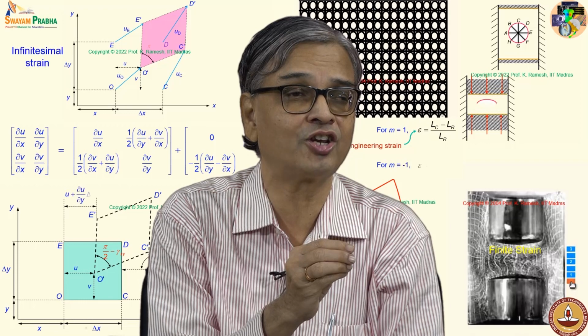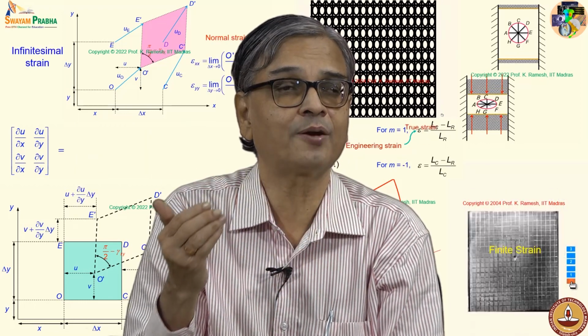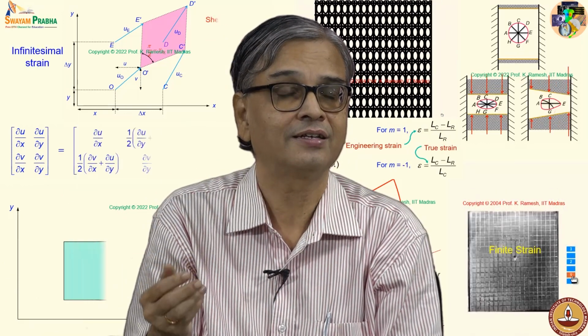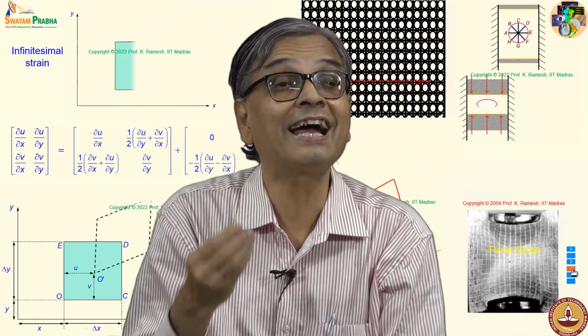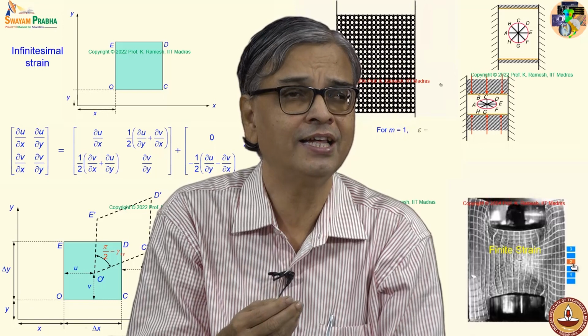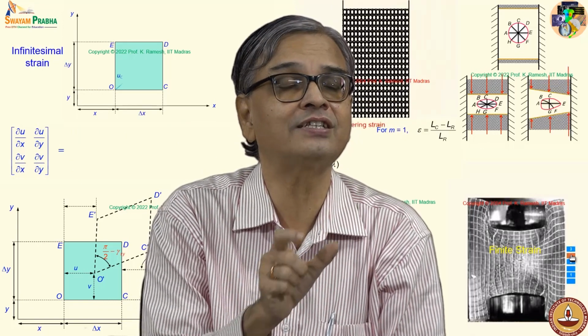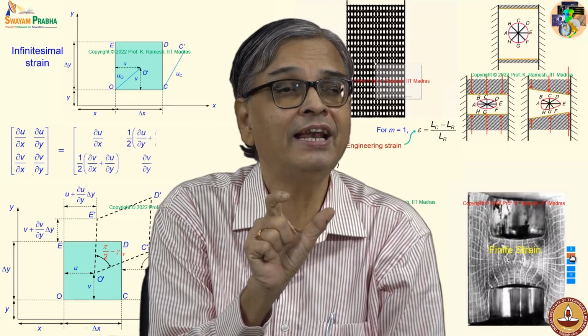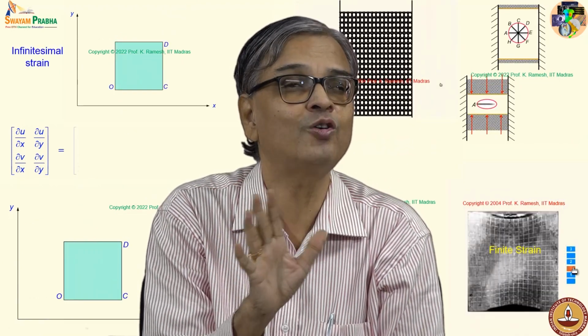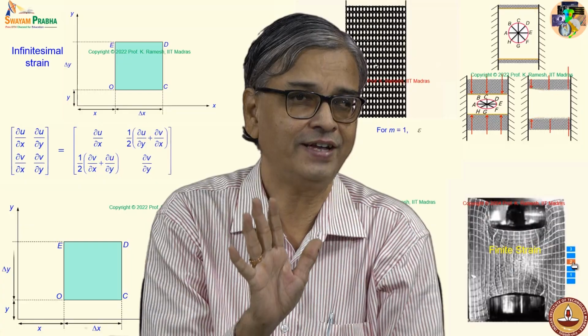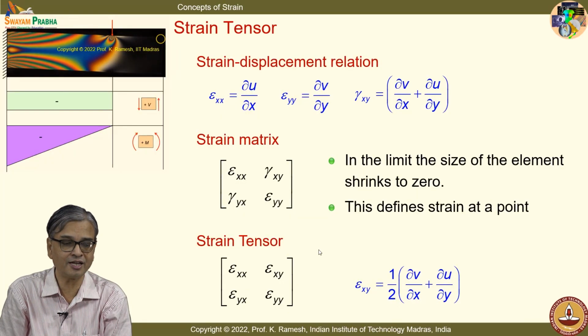Whatever stress transformation law we have looked at, I will have a counterpart as the strain transformation law. If you have looked at principal planes, I can also have principal directions here. Instead of a plane, you have a direction in which the element only elongates or contracts. It does not go through any angular changes. Fine. So, all these are similar concepts.